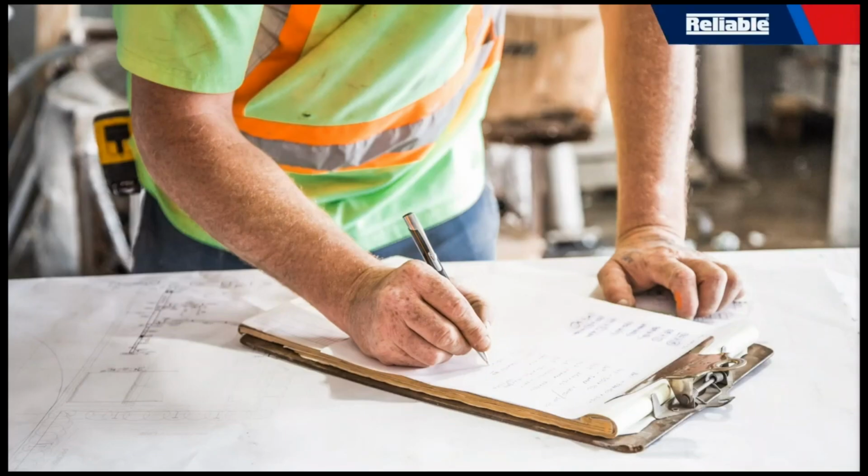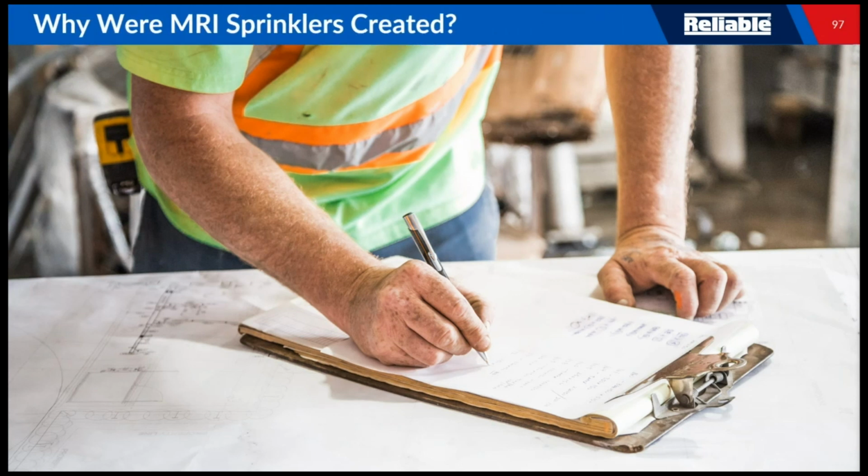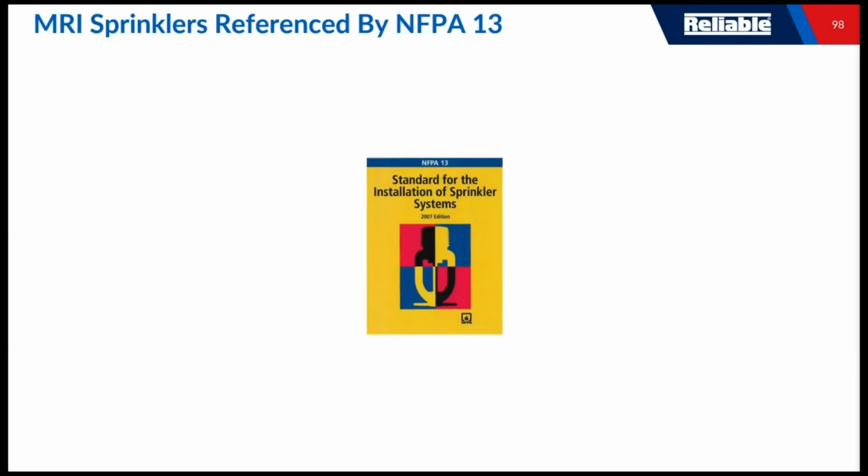So why were they created? This is another one that Reliable heard from our customer base, heard from the healthcare community, that there was a concern about regular sprinkler technology in this space. They wanted to protect their machines. They wanted to protect it in a way that didn't create damage to the sprinkler system or potentially injure patients that were in the MRI. And that just set our engineers off onto the project of trying to take an existing sprinkler for us and then get as much of the ferrous components out of it and create that non-ferrous version of the product.